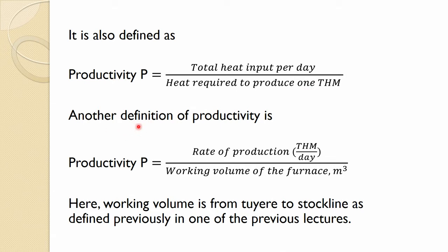And another definition of productivity is in terms of rate of production, ton of hot metal per day, divided by working volume of the furnace in meter cube.